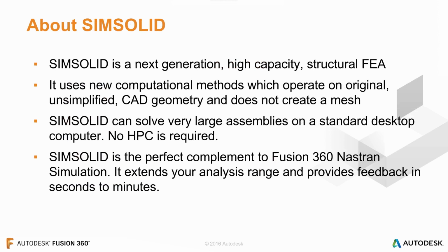The other thing to know about SimSolid is it solves two types of models that are very interesting. One are big assemblies. So if you have large assemblies that you don't really want to tackle with traditional FEA, that's a target for SimSolid. The other thing is really complex geometry. So a lot of these lattice-based design type things, they're very complicated, and that's another kind of sweet spot for SimSolid. So because of that, SimSolid is like a perfect complement to Fusion's embedded Nastran. It extends it for big assemblies and these complex parts, and that's where I think it really fits.